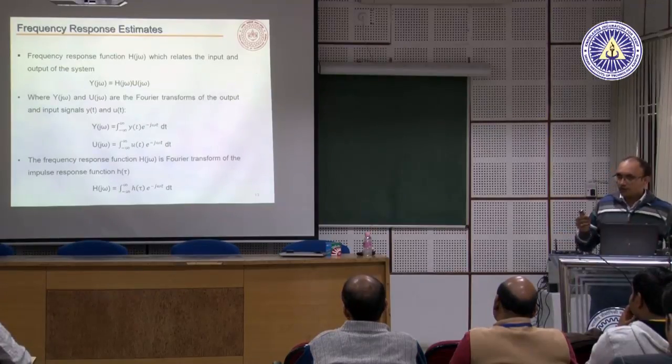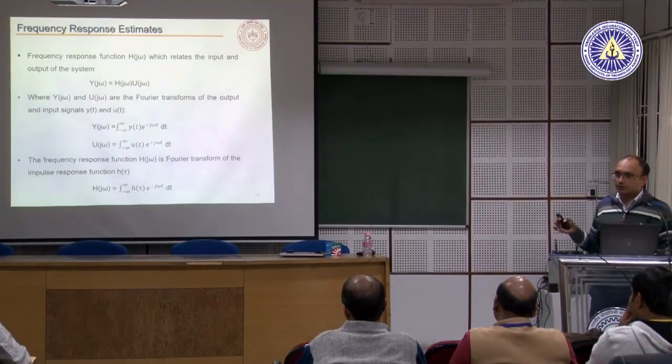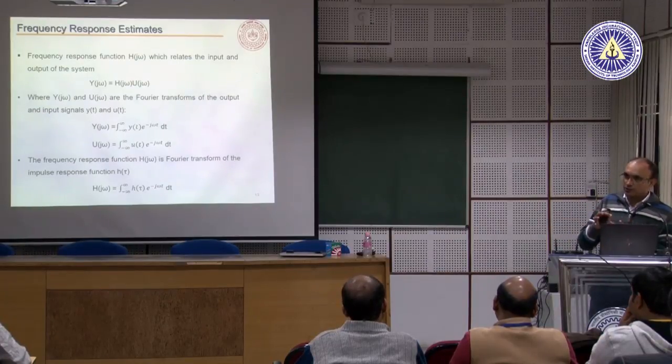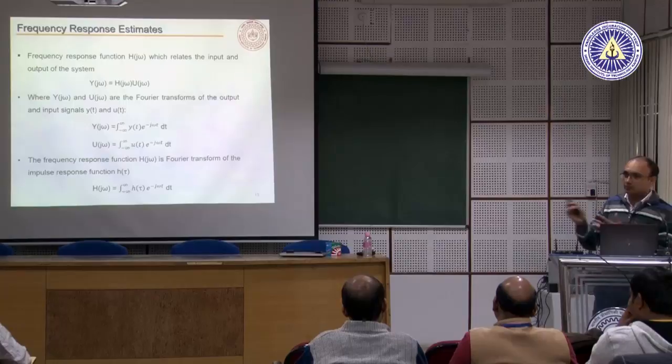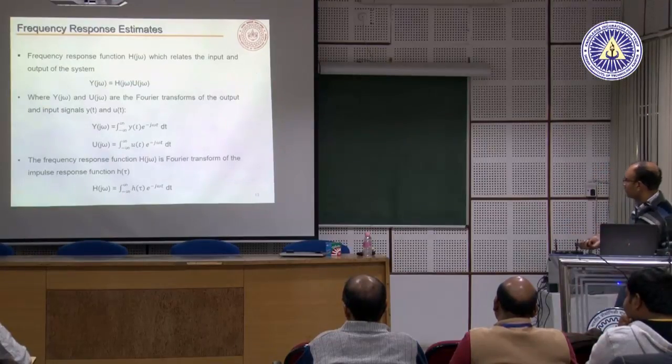So if I want to find out the response of a system to continuous inputs, what we do is relate the response of the system to your impulse input, and then we make use of this Duhamel or convolution integral to get that. So a similar kind of thing is being done over here.